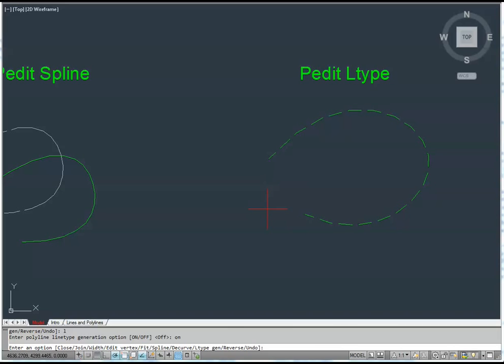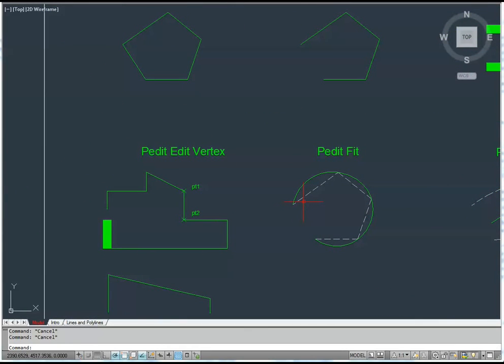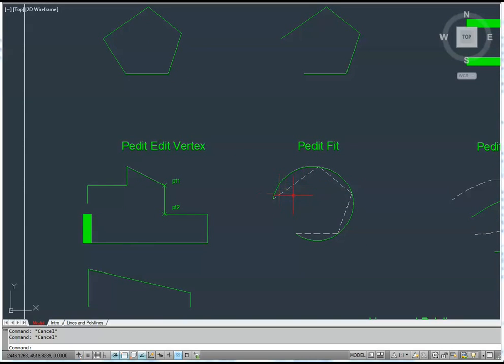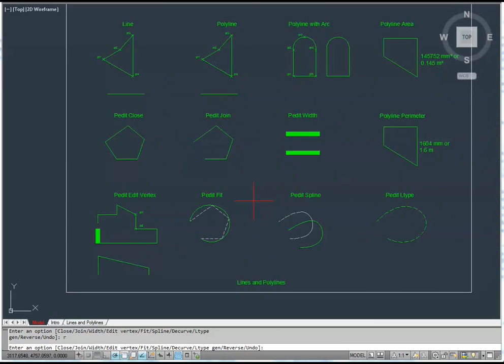And I think that's about it. The only other thing is reversing the direction of a polyline, and this is useful if you're using the measure command or the divide command to copy an object along it and using it as a path, because it'll start from one end. All you're doing is saying this is the beginning of the polyline. I'm reversing the polyline, so this will become the beginning. So for instance, polyline edit, enter, reverse, reverse. You can't see anything happen, but what it's done is flip the beginning from here to here, or vice versa. So that's polylines.